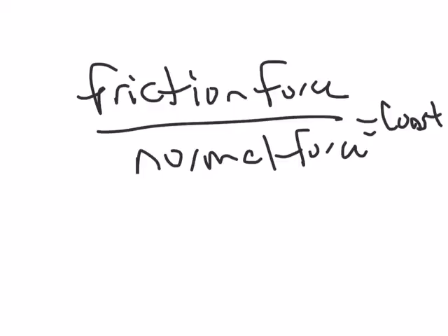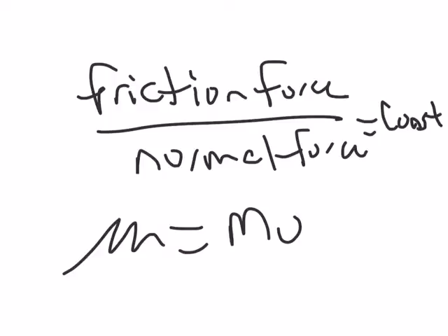If you look at page 11 on figure 1.8, mu is the coefficient or the symbol we use for determining friction. So if you looked at figure 1.8, you can see a coefficient of friction of 0.2, and then the percent of wheel slip in heavy rain.